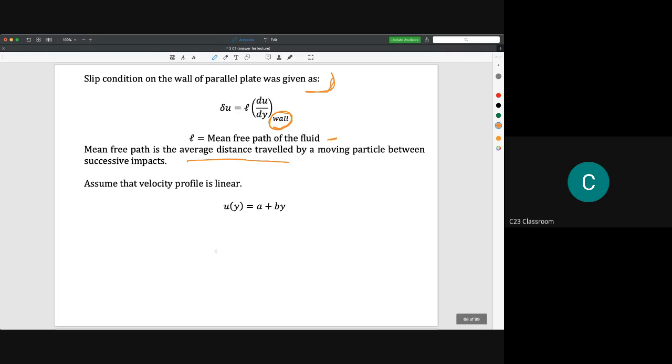Okay, and then we assume that the velocity profile is linear, because it refers to the previous question. Whether the n there means the du/dy. Normally we have tau equal to mu du/dy. For Newtonian fluid we assume that n is equal to 1. n can be less than 1 or more than 1, which refers to shear thickening or shear thinning fluid.